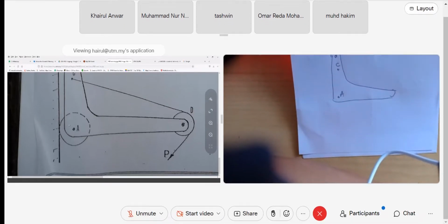Okay, so remember A is roller, only one component, only X direction because the normal to the surface is vertical, right? So only one component. We have AX only. Since it is a roller, the force acting on the roller is only AX. Even though this member L shape is on a pin, since we only have AX from the surface, it is just a roller, that's why we call it roller. So only one component, AX only.